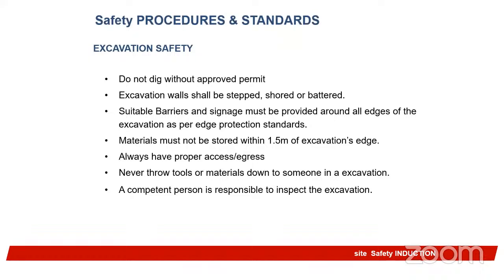Even if you want to create the barrier at the edge, there will be a distance, maybe 1.5 meters or so. My barrier must not be within 1.5 meters of the excavation edge. So 1.5 meters, you have your barricade. Then what I want to happen should happen outside, unless there's a particular need to work simultaneously. And there are procedures for what we call simultaneous operations. They are called SIMOPS. There is also a safety control standard for that.